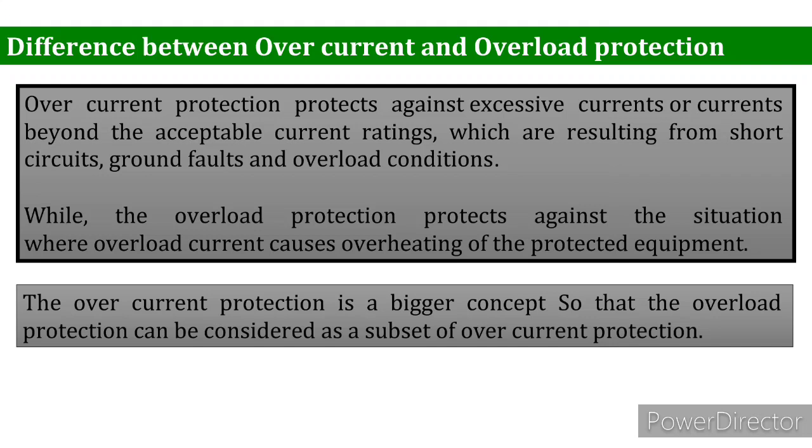Overcurrent protection is a bigger concept, so overload protection can be considered a subset of overcurrent protection. The overcurrent relay can be used as overload protection when protecting resistive loads.